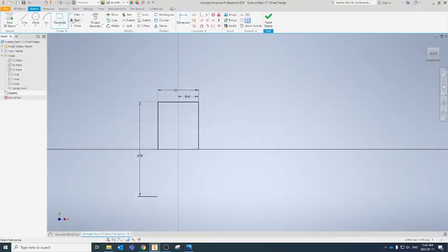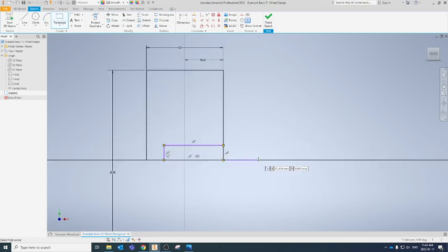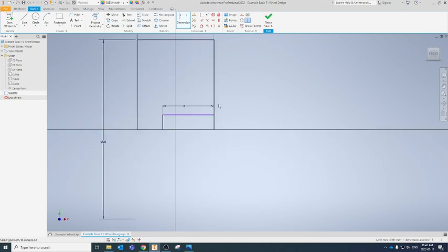So I'm going to do that by creating a 2-point rectangle right here, and I'm going to say, okay, my axle is going to insert from this side into my wheel, and let's just dimension that. I'm going to dimension this so that my axle will insert 8mm into my wheel, and just like I did the linear diameter over here, I'm going to do the same thing for my axle. So I'm going to dimension from this bottom line to the top of my rectangle, right click, linear diameter, and I'm going to type that in as, let's go 4.5.